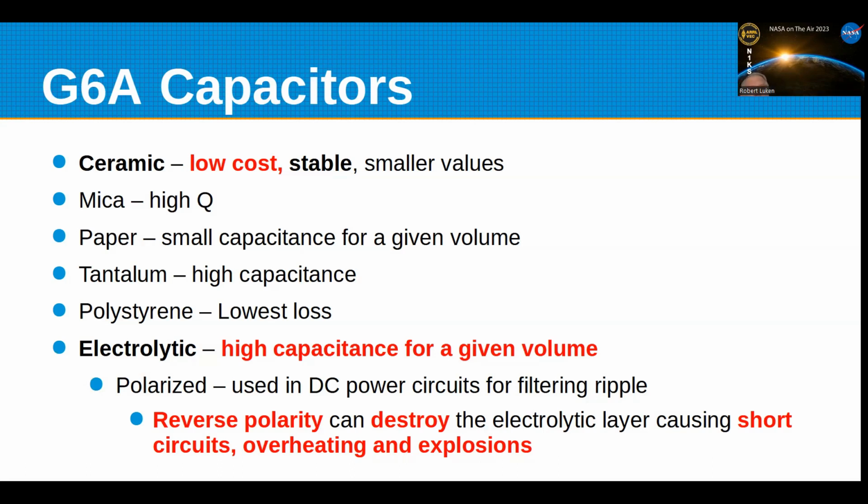The electrolytics are polarity sensitive, and if you hook them up backwards, probably the best thing that can happen is they swell up and leak. The worst thing is they can actually explode, and you get all kinds of paper stuff floating in the air. It's messy.